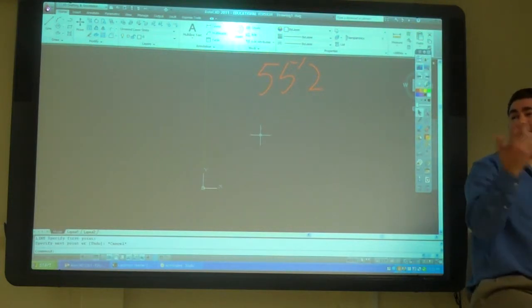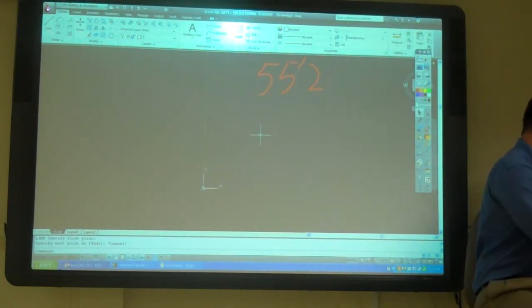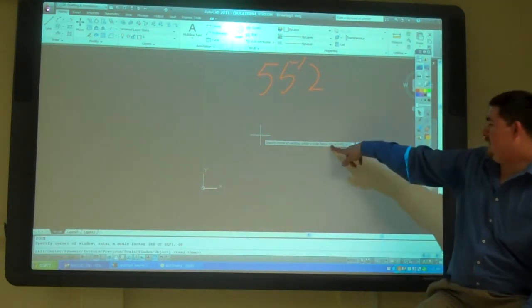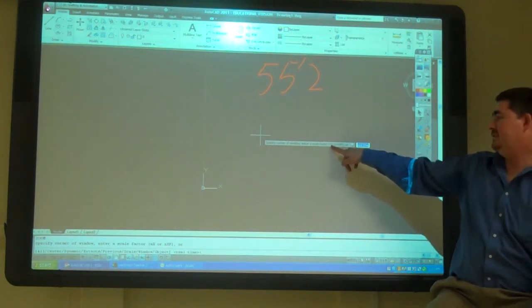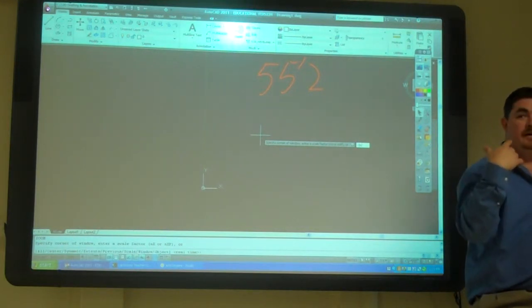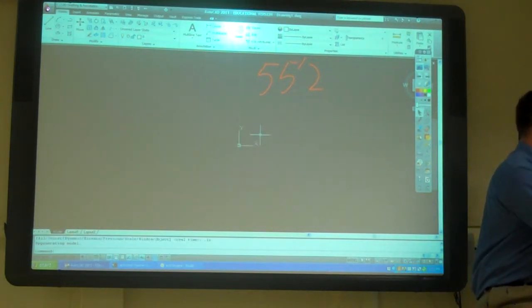If I type Z, take the zoom command. One of the options I have is X, the NX for a scale factor. So I can say 0.1x, so it's going to be 1/10 the current scale factor. Enter. Kind of scales it out and resets it.